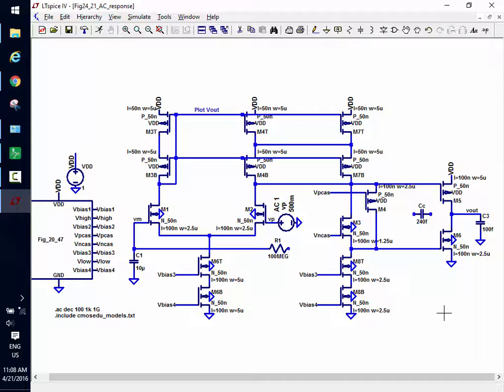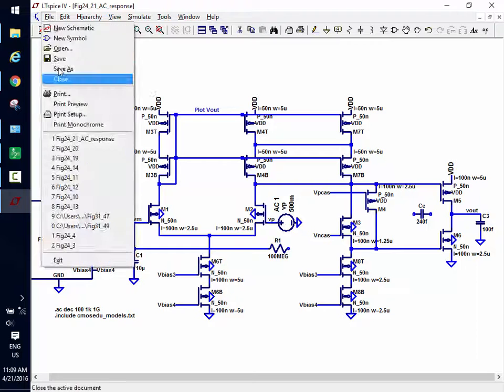So if I want to increase F2, what do I do? You'll need to know this. Increase the widths of these. Now, when you have a 1K load to ground, this guy's going to be supplying more current, so you may want to play with the width of this one independent of all these others, because if it's always driving a resistor to ground, it's always going to source more current than this one will, which is connected to ground.